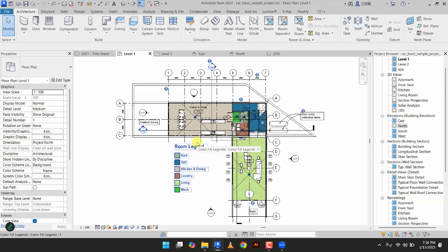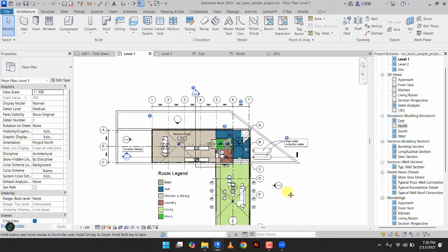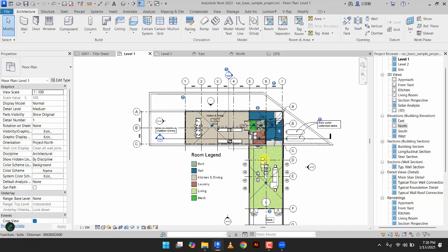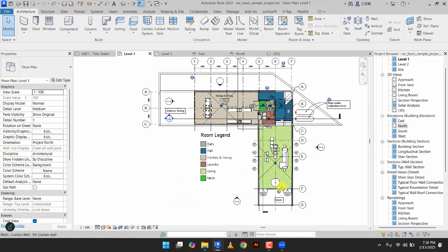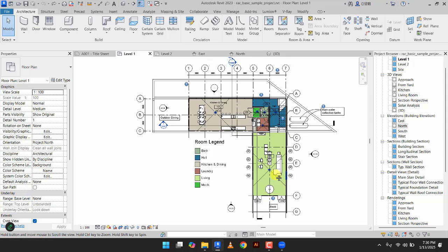And how do you pan? Pan is moving around this way. Okay, this is what I mean. To pan, use the same scroll, but this time you're not going to scroll it. You push it down, right? Once you push it down, then you move. Then it gives you that panning effect. So you can pan anywhere.